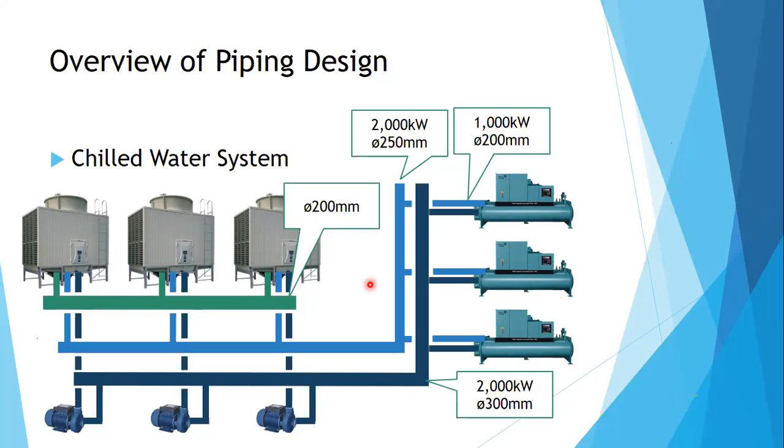Your main pipes are only the combination of your distribution pipes, so it's easy to calculate. And we have the table to use according to standard pipe size. If your pipe size is bigger than what is on the table, you can easily calculate, as long as your velocity is maximum at 2.2 meters per second.